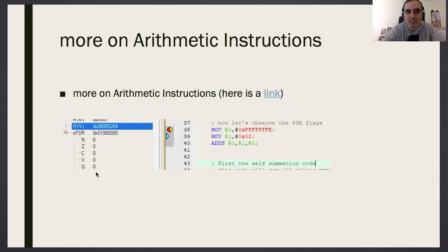If one of the flags changes or not. And this will prove, for example, that move does not move the most significant bits, because this is a negative number, this is a positive number, and this is -2, by the way. If this was LDR, after this operation, the summation would have been 0, and Z flag would be 1. But since I'm using move, these are not going to be moved. It's going to be FE, which is a positive number, 000000FE, actually.